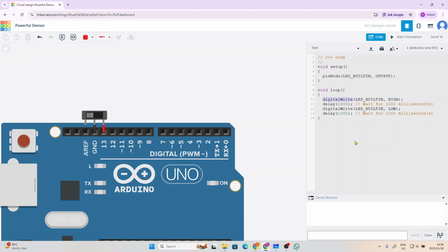Analog, on the other hand, think of it as a wavy thing. It can go from 0 to 5 volts. However, it's not a true analog pin in the sense that the board doesn't actually go to 5 volts. Instead, it uses something called PWM, which is what we call pulse width modulation. What pulse width modulation is, is simple.